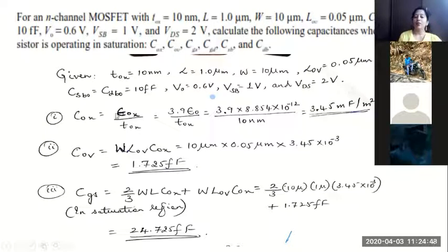Okay. So you remember capacitance is found as epsilon A by D. So this D stands for the distance or the length, and for area we are using 1 per unit area. So the oxide layer capacitance is calculated as epsilon A by D, or in this case it becomes epsilon into 1 divided by D, which is given as the value TOX, 10 nanometer. And how do I find this oxide layer capacitance for silicon dioxide?